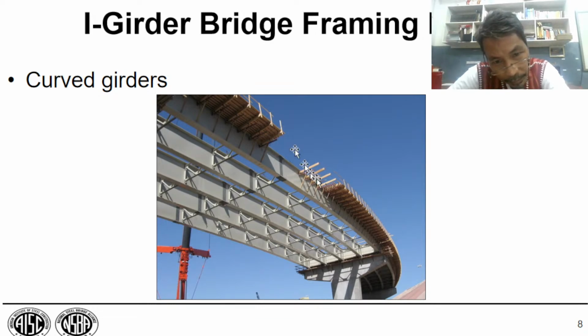So we have what? They are just making the formworks and false work. So this wooden diagonal wood support, they are false work. This part, wooden parts are formworks, meaning this bridge will have an overhang, and the type is reinforced concrete overhang. Okay? Do we follow? And you'll notice the column is one column and pier type of support, which is in the form of what? Reinforced concrete. The material, reinforced concrete material.